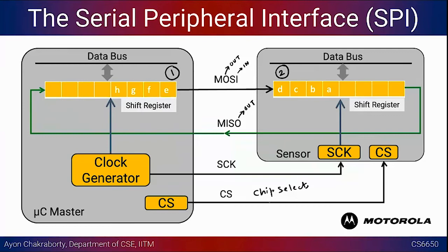There are many terminologies for the same pin. Sometimes they call it slave select, right? Sometimes it is also called CE or chip enable. So this is the pin that is going to select a particular peripheral device or a particular sensor. So you will turn on one of the sensors, then give it the clock, and then send data to that device or read data out from the device. So this was all about the SPI interface, the associated pins and so on.